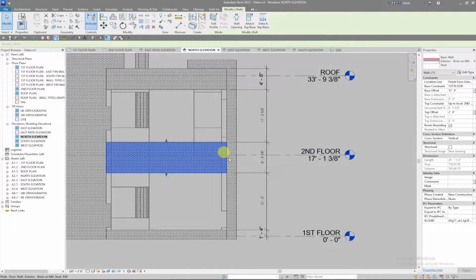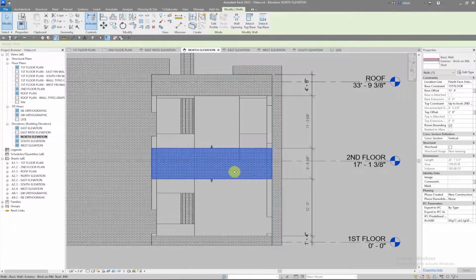So this is a great example of how in Revit sometimes you can get the desired outcome, but the settings aren't exactly what you would want them to be. So, I could get this coming up from the first floor, or the top of this wall would be referencing the first floor, but that's kind of a silly way because this wall really exists on the second floor. So we want to show it above the second floor. So by figuring it out from the first floor, we've figured out the dimension, then we can go back in and change the settings.